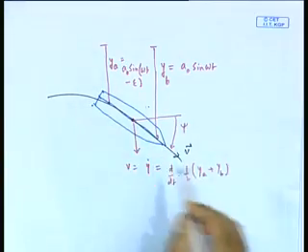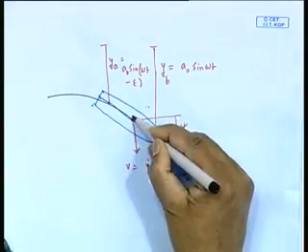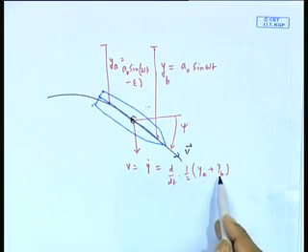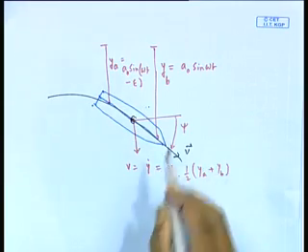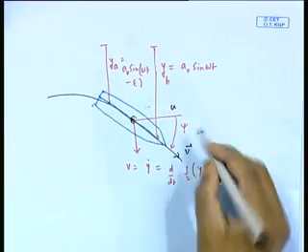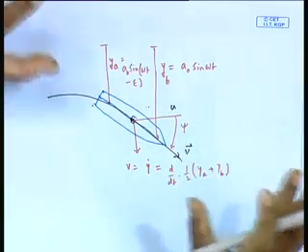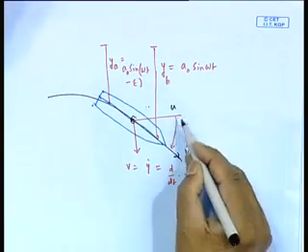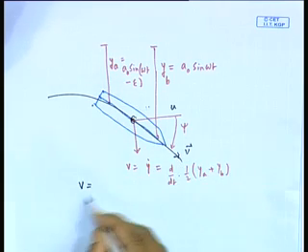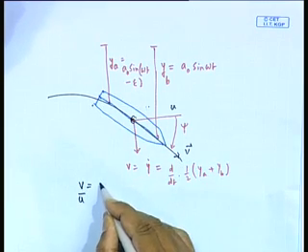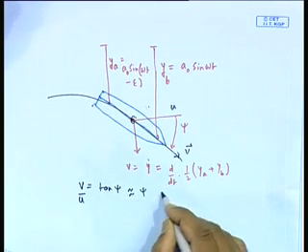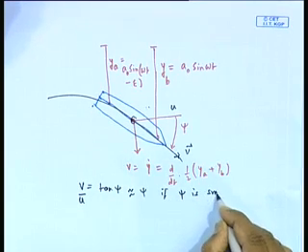The question is that, see what is happening here. Now, what is the velocity here? This velocity here is given by v as y dot, d by dt of half y a plus y b. Agreed? This is my v. What is this psi? Now, you should remember this is v and this is u. Actually, this psi is always a small angle. So, u and v are close by, although this diagram shows a very exaggerated one. Now, v by u is equal to tan psi. Of course, it can also become equal to psi if psi is small, which is what we will be taking.